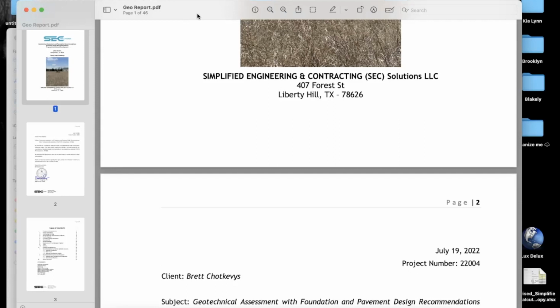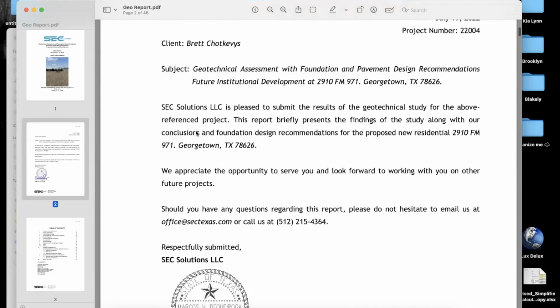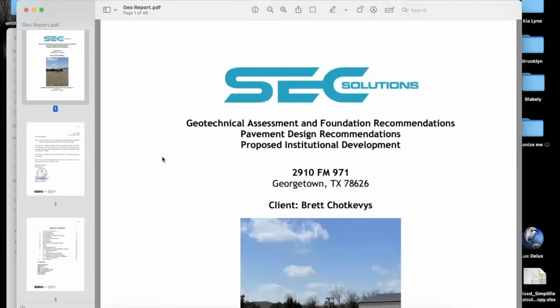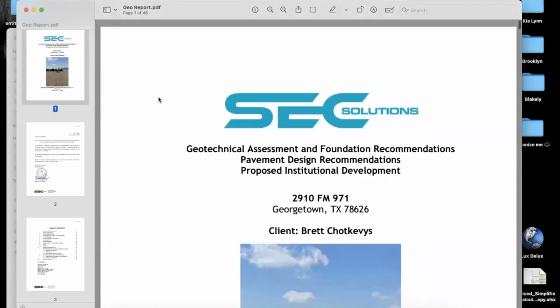The longer you get, the more tension, right? Like you're potentially going to buckle. And so it's super important to have that soil report done and have them spec out what type of slab you're going to need for this kind of stuff. So that's the geotechnical study. And I didn't get that done until a few steps into this whole process.